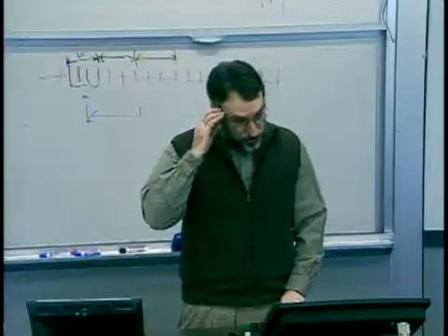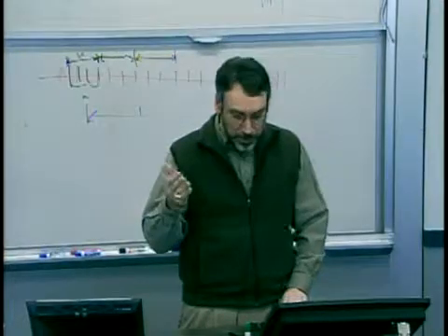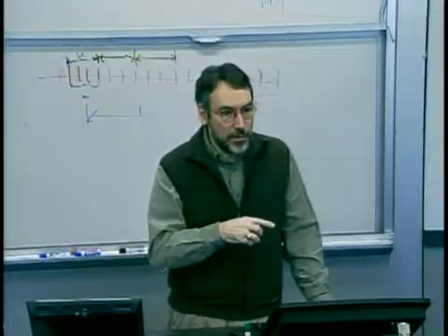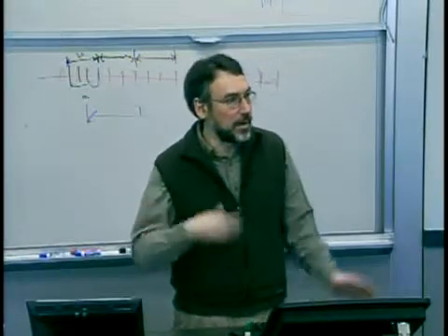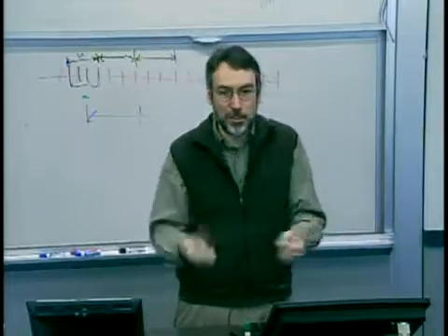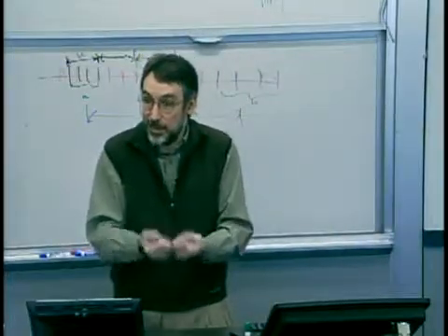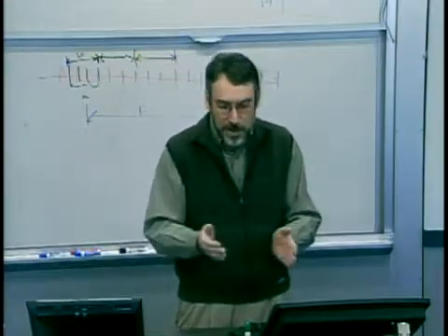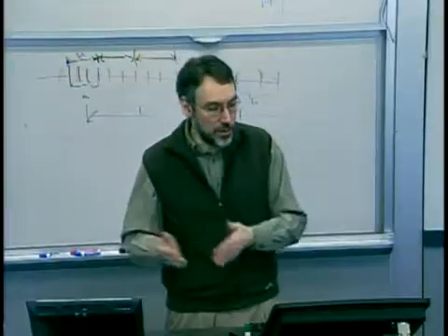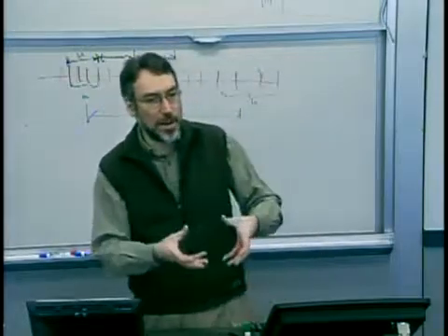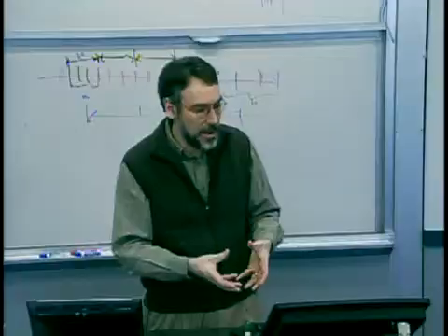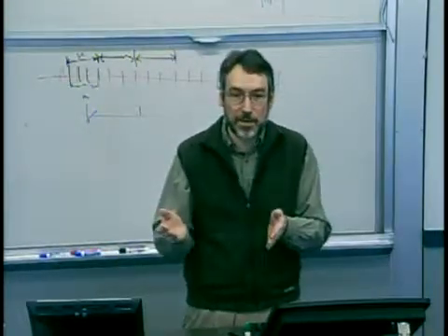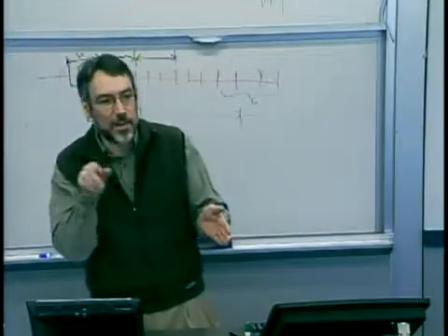One of the things you use these CPs and CPKs for is in manufacturing, and you can also use it in design to get a quick feel for the relationship between your manufacturing capability, the inherent spread and mean to target centering, compared to your design specs. So you can characterize your CP and CPK and then evaluate, well, if I make some change in my design spec, what would that do?